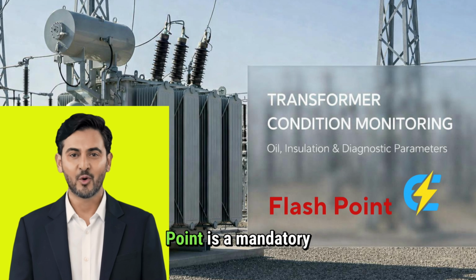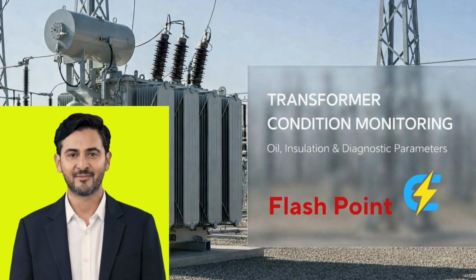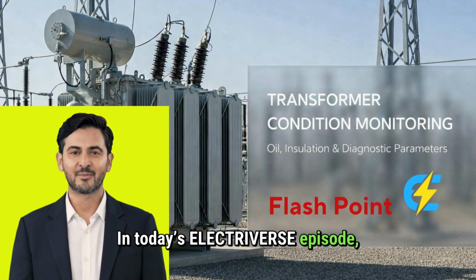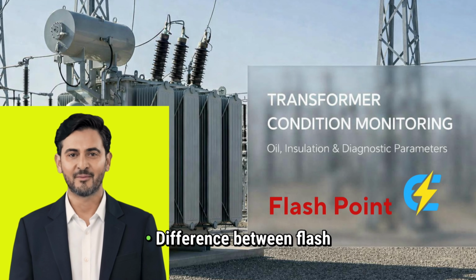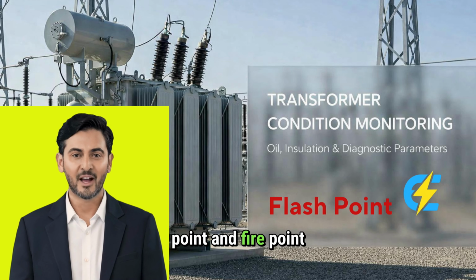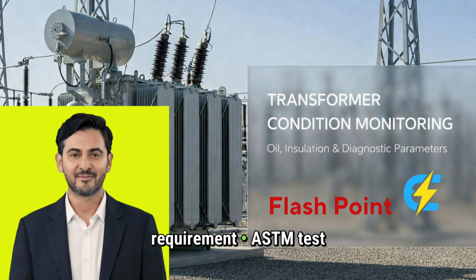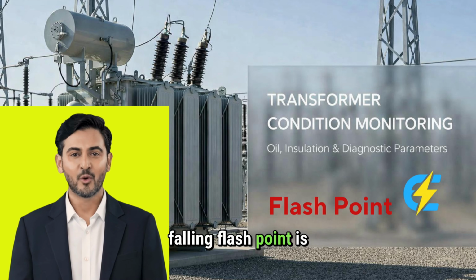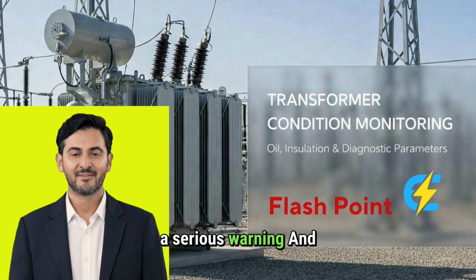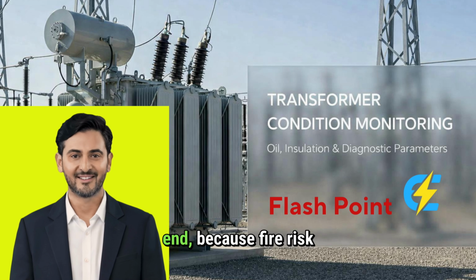That is why Flashpoint is a mandatory safety parameter in every transformer oil standard. In today's Electroverse episode, we decode what Flashpoint actually means. Difference between Flashpoint and Firepoint. IEC 60296 minimum requirement. ASTM test methods used. Why falling Flashpoint is a serious warning. And how engineers decide oil rejection based on Flashpoint. Stay till the end, because fire risk is not negotiable in power transformers.